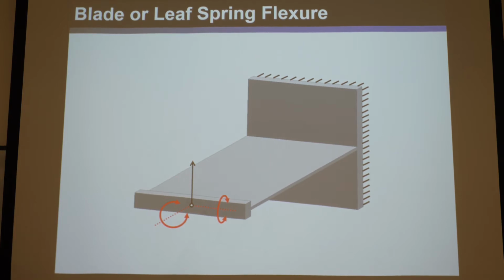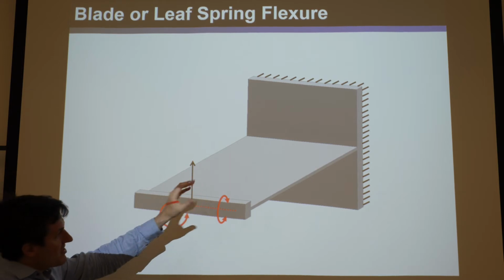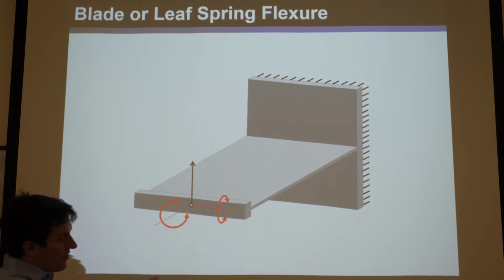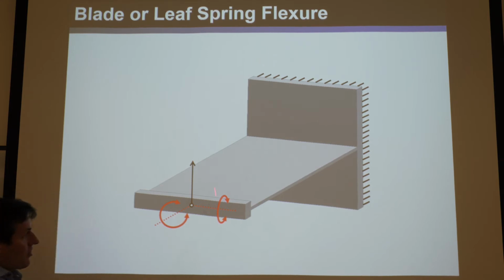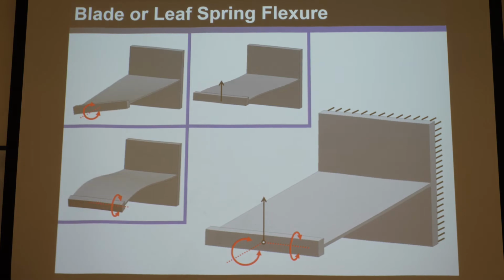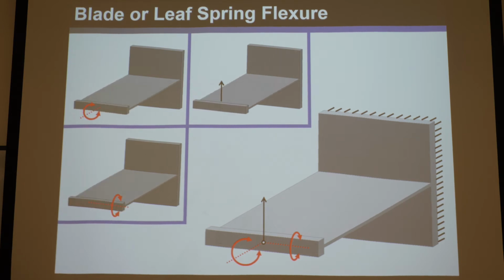Some people call it a leaf spring flexure, but it's a blade flexure. It's just a flat sheet of paper, almost a flat plane. And it can connect 2 rigid things. And these are the correct degrees of freedom it has, which, let me show you an animation. Here's the first 3 mode shapes. They're associated with natural frequencies that are much lower than the other higher mode shape natural frequencies. Okay? All right. And so very good. So that's how it would move.